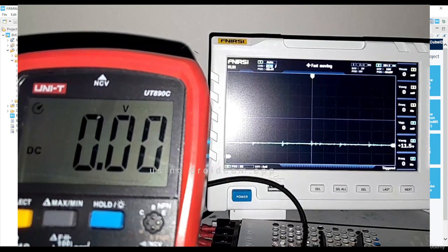And of course there's a slight offset there to what we set up in the code, which is 10 volts. In essence, how to deal with this is basically to average the voltage more, or to use a more precise voltage sensor, which of course will affect the loop, so you'll have to incorporate this into the loop design. Or another thing you could do is simply adjust the reference, the VREF, and make it slightly lower, understanding that there's always going to be an offset in your output. Just find out that average offset value and change it.